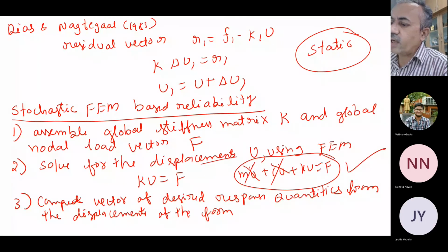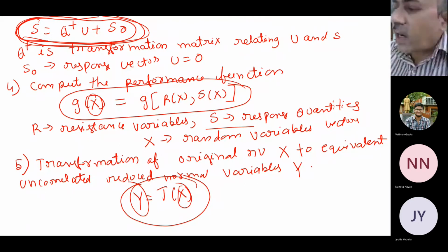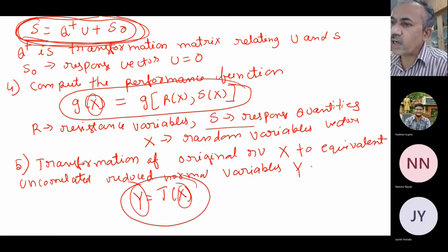And then finally, what we are saying is, the stochastic FEM essentially says, for reliability analysis, you have a performance function, and you have R, S, and other things there. So you will write these types of expressions. Your finite element equation is basically Ku equals F only. Because you are treating Young's modulus, or several random variables, the only thing you have to do is find the derivatives of this S or resistance or something like that.